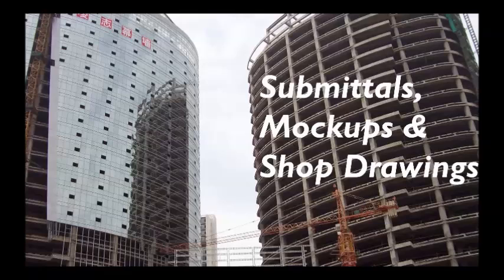And they'll draw it up. And then maybe the architect will make some little revisions or notations, and they'll stamp it and sign it and say they approved it, or they approved it with changes. They could reject it and ask for new drawings or different drawings, but usually it's kind of a back and forth process working through the shop drawing phase. And typically it's going to be during construction when the manufacturer and fabricators are involved and on site.